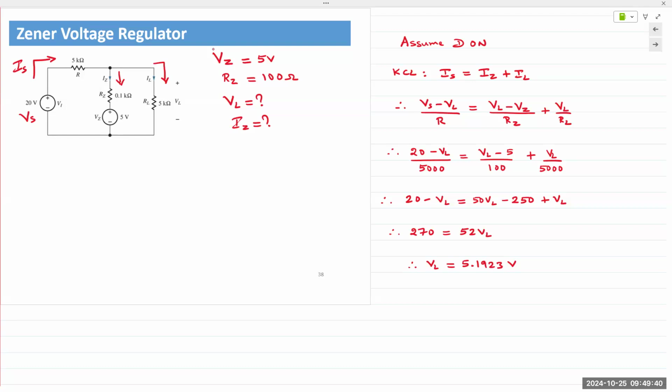But schematically speaking, we draw it as a resistor in series with that Zener diode. So when we connect any load in parallel with a Zener diode, we have to take into account the Zener resistance. The diodes are fabricated to take those resistances into account. So even though the Zener voltage is rated as 5 volts, the output voltage is 5.19, 5.2 volts. And this is something we'll simulate and perform in the lab next week.